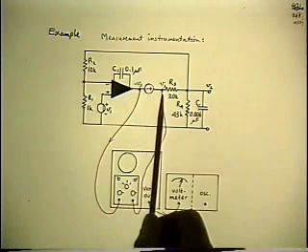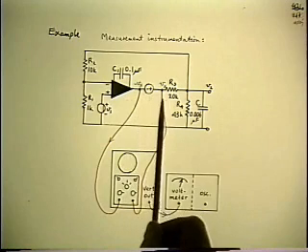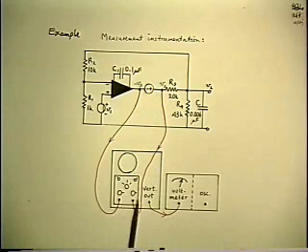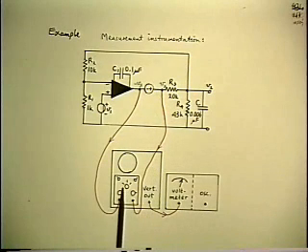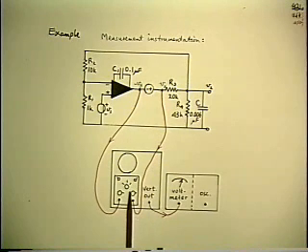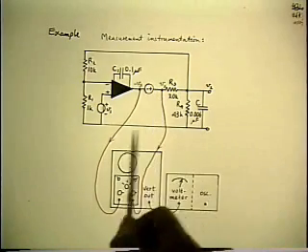The two voltages we want to measure, the ratio, both magnitude and phase, which is the loop gain, is Vy over Vx. So I put both of them into a dual channel preamp for a scope. You can see this is historic because this represents an old 500 series Tektronix. And what you have available is a selector knob that says you can observe on the screen either Vx or Vy.